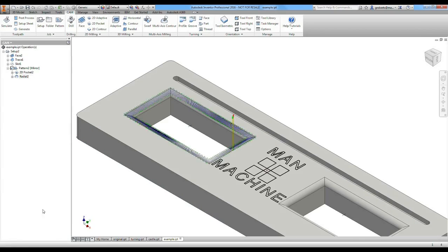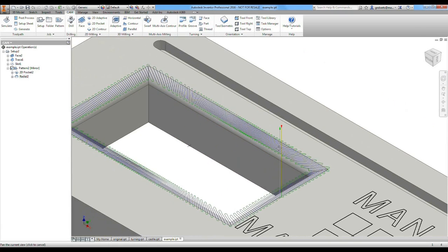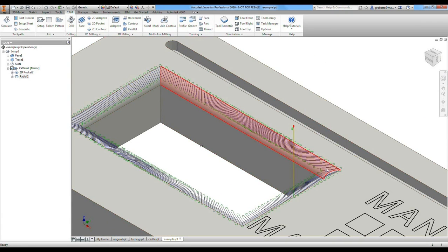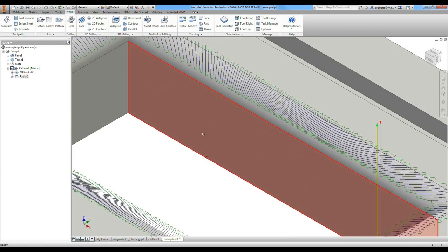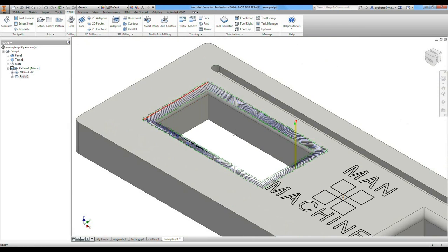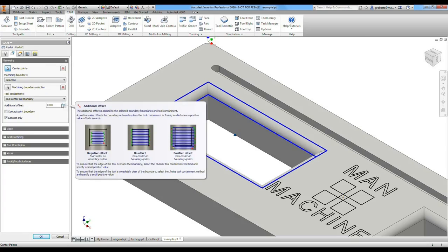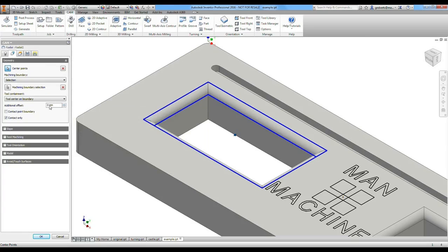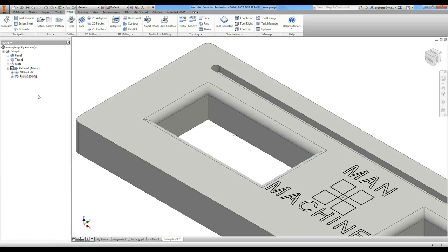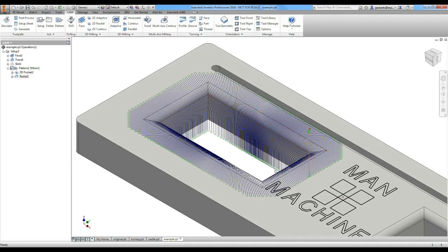and you can see the radial toolpath being created. It doesn't extend past the top and the bottom. Obviously it does in the linking, but to give a better finish, we want the toolpath to extend past the limits of what we selected. So we'll edit this radial toolpath, come back into the Geometry tab, and this feature allows us to extend the toolpath past the area that we've selected. We'll just add it up to 5mm, that's OK, and you can see it extends past by 5mm both sides.